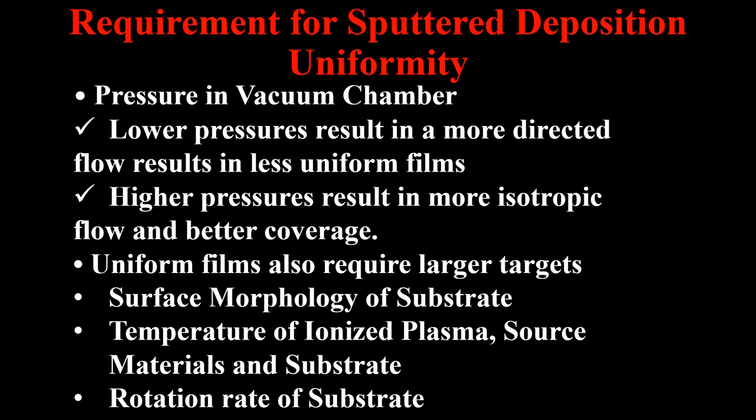So the rotation is very important in terms of uniform deposition. It is not only important in high vacuum based techniques, but rotation is also important in solution based deposition techniques of thin films, and that is the reason many solution based techniques use rotation devices in order to get a uniform coating over the substrate.